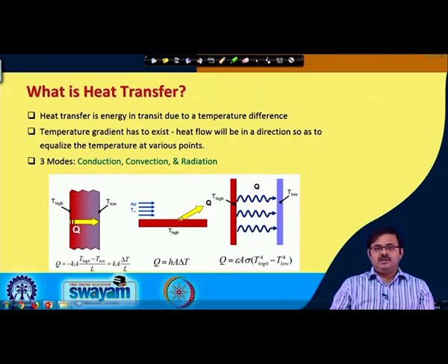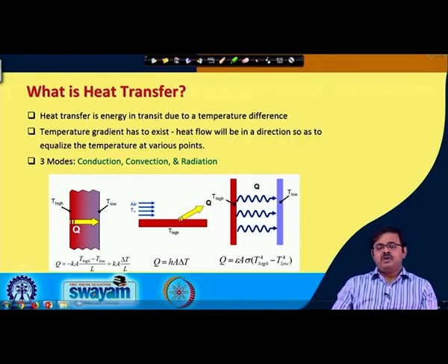and something whose emissivity is lower than 1 is a non-black surface. Okay. Emissivity can be a function of wavelength, and sometimes what we do is we take an average value of the emissivity over the thermal wavelength range and give it a constant value, and that is called a gray body approximation.